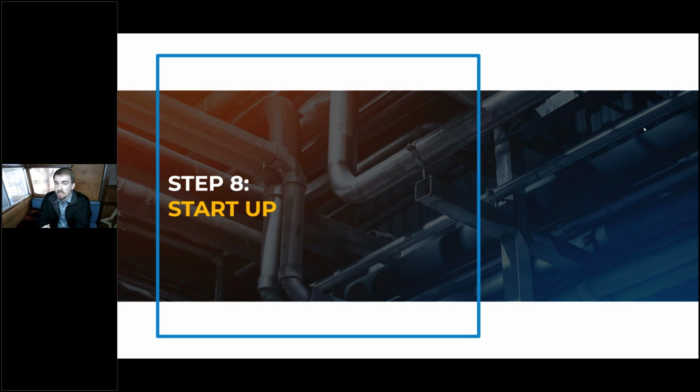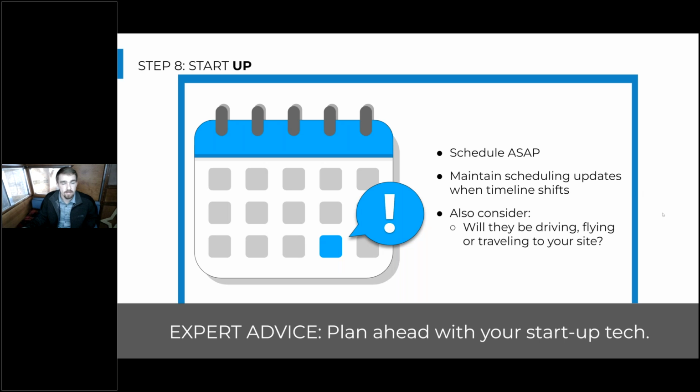Usually not in series directly with the heat pump water heaters, but I've seen instantaneous boilers in parallel as well, as long as the controls are coordinated well and they're not fighting each other to fill those tanks. Because boilers are usually a lot higher BTUs. So if you have the heat pump fighting the boiler to charge the tank, usually the boiler is going to win, and most of the energy being used to heat that water is going to come from the boiler. Yeah, I hope that answered part of the question. Definitely send me follow-ups, and if we get to the end here, we can refer back to that schematic and I can walk through it a little bit more closely.